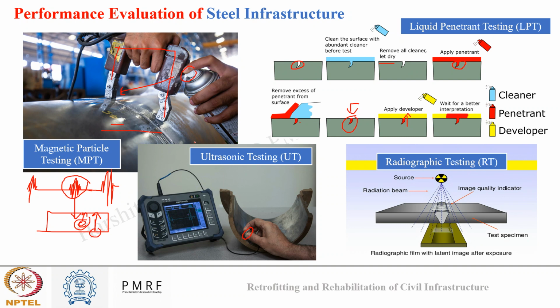Okay, in this radiographic image, the distress will appear as a dark or a light area on the image, because through the distress, there was loss in my signal strength or my input signal. Okay, this thereby will help an inspector to identify and evaluate the extent of distress in the steel structure.